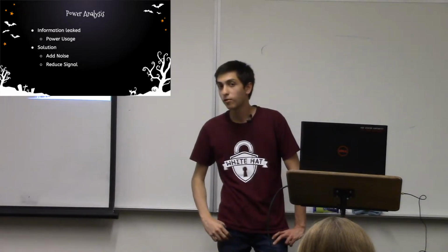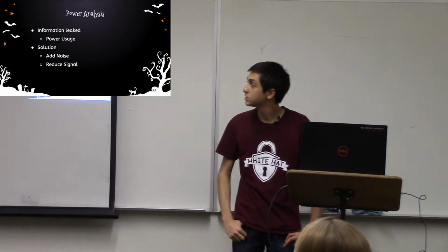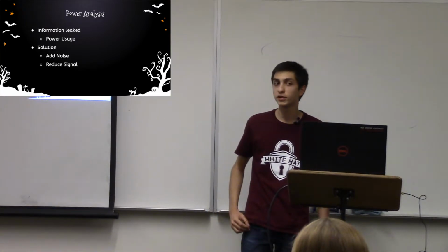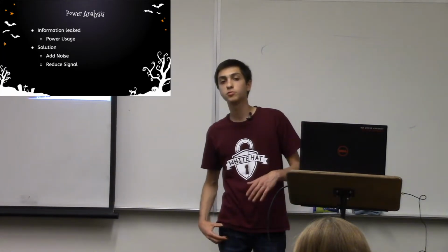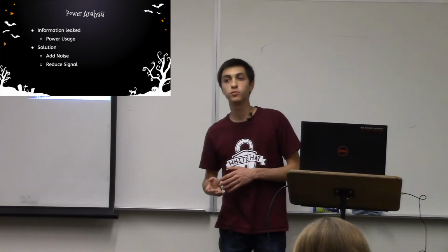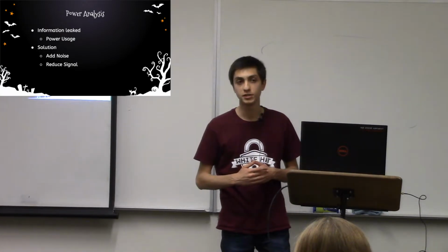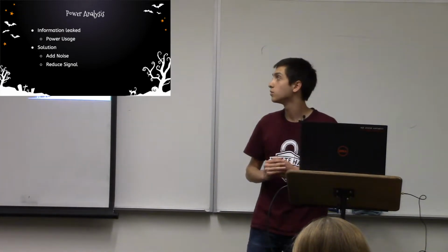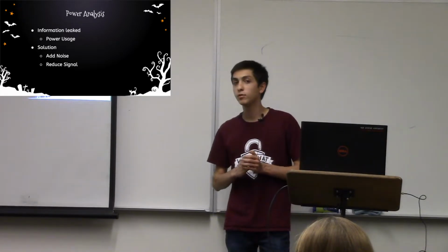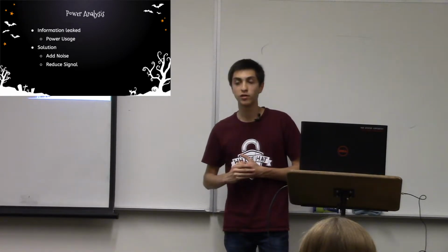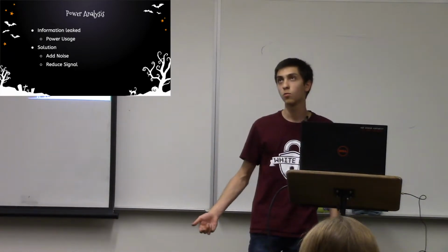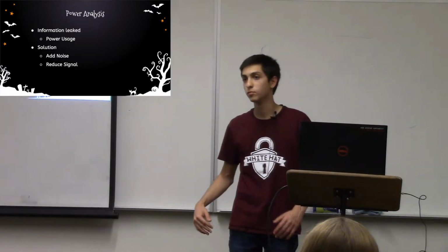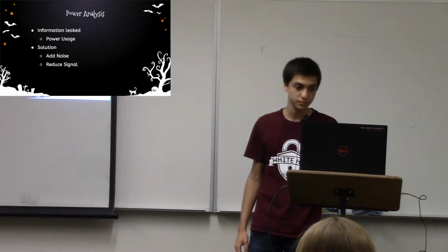And the solution to power analysis is to add noise, which is basically to do random operations in the background so that you're not able to attribute certain power usage to an operation. And also reduce signal, so maybe make all operations take the same amount of power, so you can't differentiate between what the input is and how the input affects power usage.